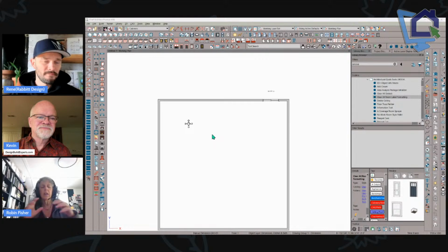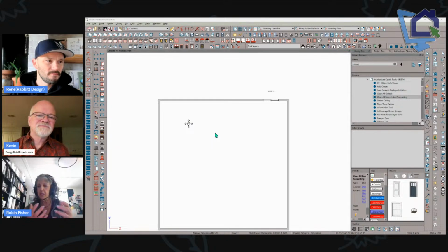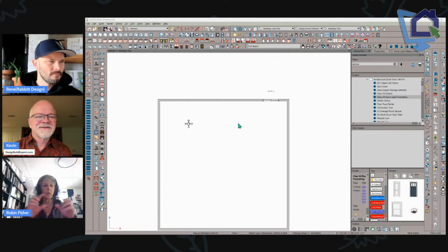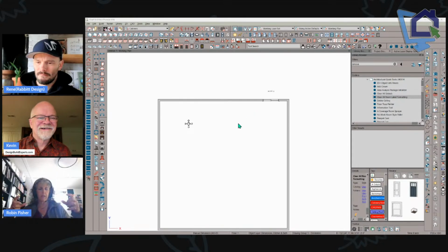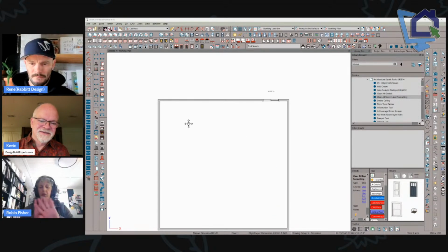As a kitchen and bath designer, you're working for interior spaces. So when you open up the defaults for dimensions, the first thing you want to do is think about where you want the line to attach to. How I have my dimensions set, I use 4 different dimensions. I use manual, end-to-end, center line, and interior.